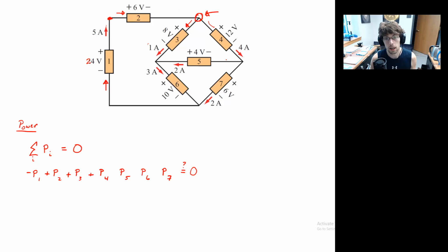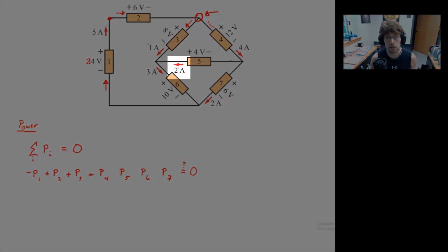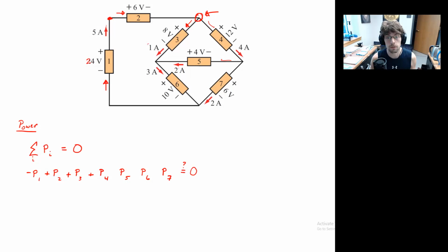Keep going. Element 5. Let's see. We're told that in that horizontal wire, the current is moving from right to left, and therefore the current is actually entering the low side of whatever this element is. So we have to put in a negative sign. So there's the negative sign. And then they recombine. Again, keep in mind that the right and left hand nodes are both essential nodes, or extraordinary nodes.